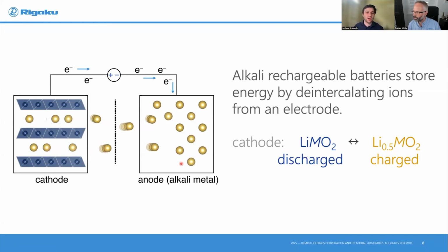And then there'll be a negative electrode, and that could be graphite or silicon or just the bare metal. In this case, I've shown it as the bare metal, lithium or sodium. And we've set these 2 electrodes up in a clever way so that in between them, there's a separator that's ionically conductive, a salt solution typically, but electrically insulating. So you can get ions across from one electrode to the other, but if the corresponding electrons want to go, they have to go through an external circuit.